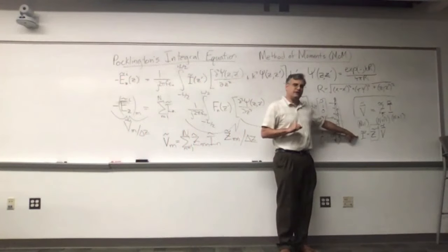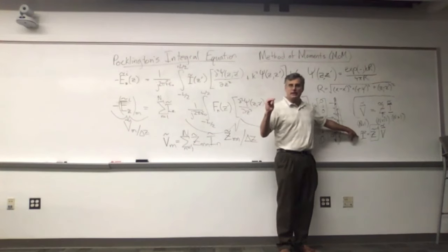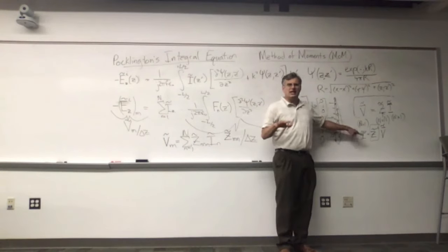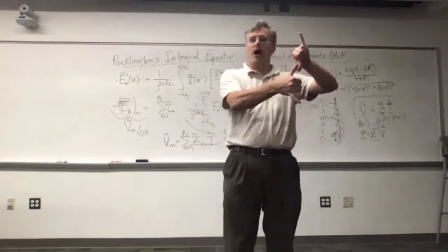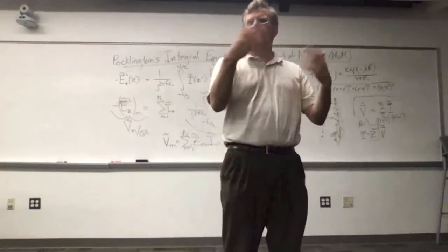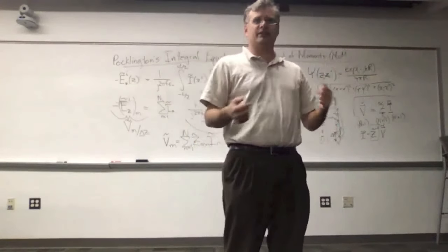You've been solving for current because intuitively, using things like that transmission line argument that I showed you in the first week of class, what I didn't tell you is that in your head, you were solving Pocklington's integral equation. It only works for really simple systems like bent wires, dipoles, and a few other things like the loop antenna, the square loop antenna.